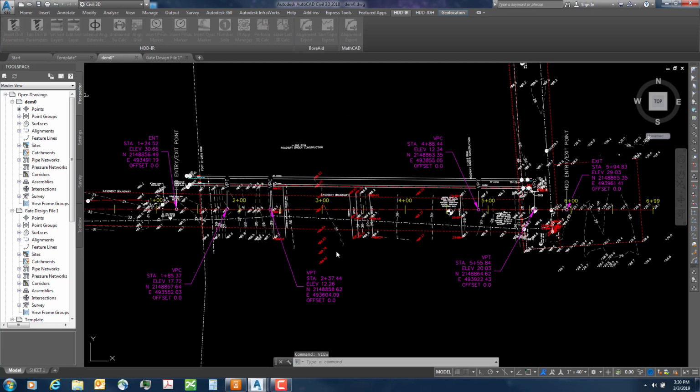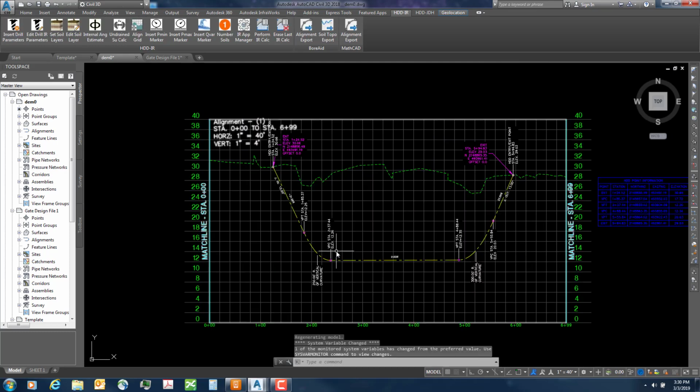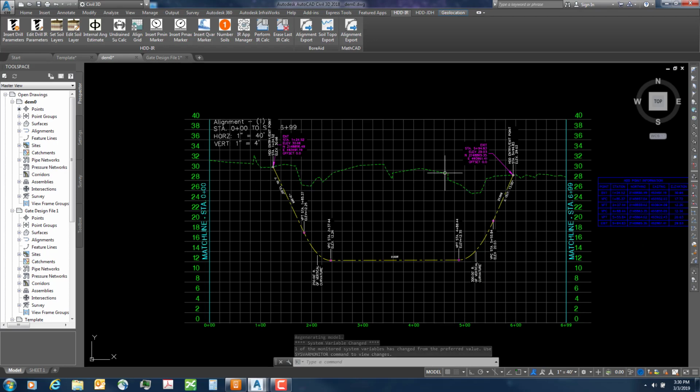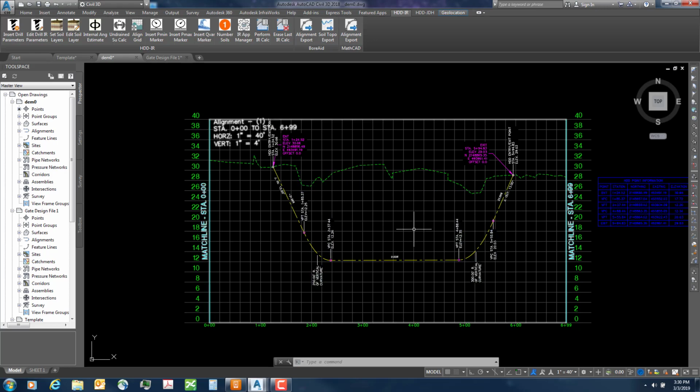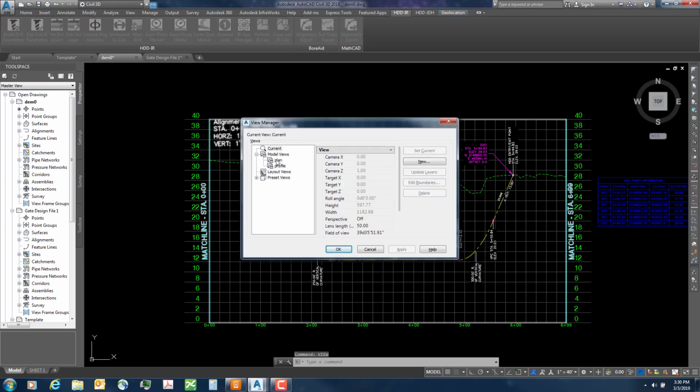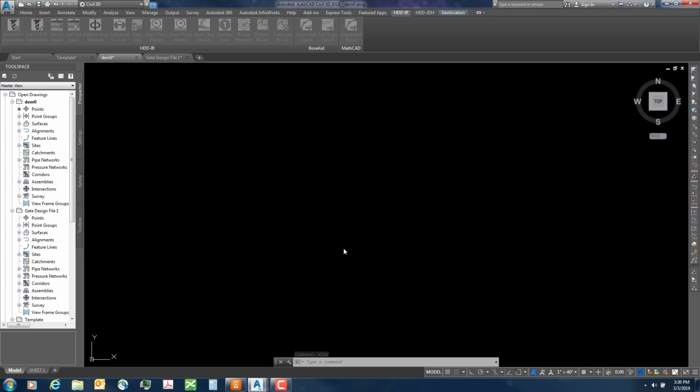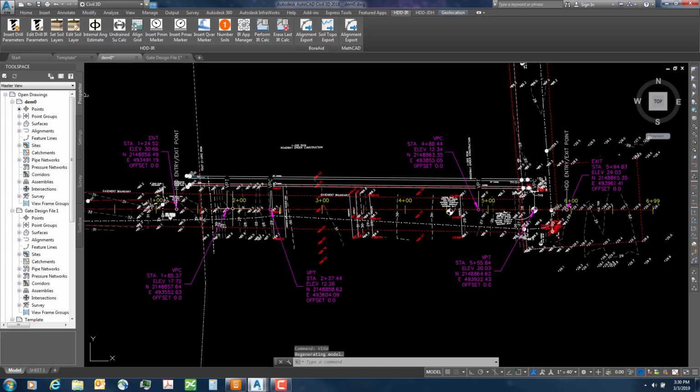So here's a layout that I had done previously. This has got the profile cut across the two lane. It's actually two lanes in each direction, and just a very arbitrary generic design. Okay, so the first thing you would do is you would plan your soil borings. So I'm going to go back to the plan view, and wherever those are taken, you can mark the same way I mark these entrance and exit points.